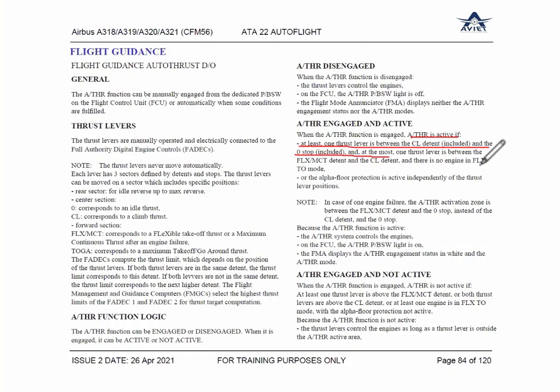One of the thrust levers has to move from the zero detent. You have two thrust levers. One of the levers has to be out of the zero detent. When it is out of the zero detent, your auto thrust is active. You can say one of the levers is at zero, another is above idle or maybe at climb. So they are at different positions. It is asymmetric thrust. But the computer is very smart. It is designed so it will take the higher side as a reference.